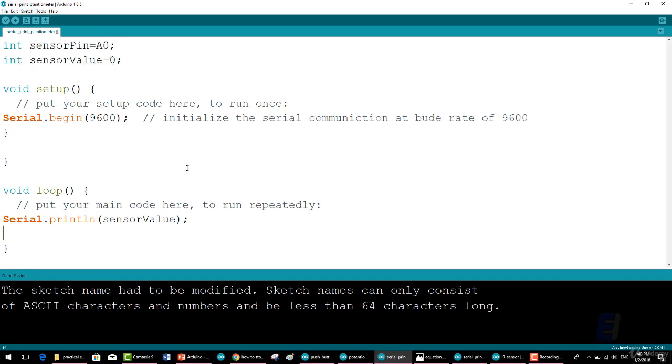Once it's done, press on the magnifying glass located towards the top right of the window. This is the serial monitor, where communication begins, sending and receiving by the Arduino. Here, you must verify the baud rate is also 9600, or else you will see garbage.